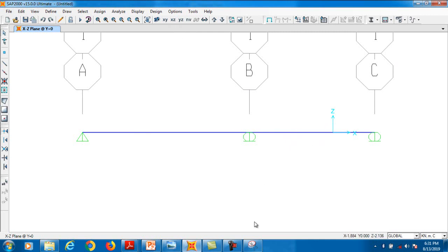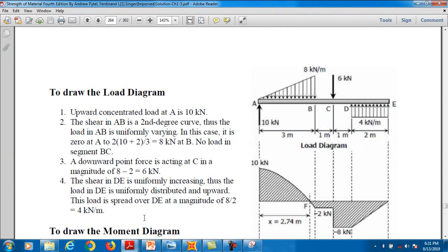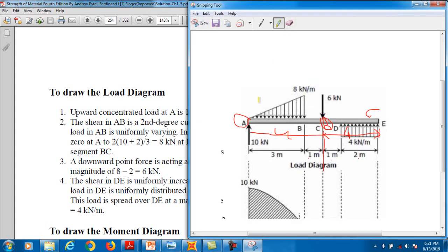So first of all, the second step is that we have to select the proper joints. Now if we come to the example, we see that there is a support and there is a support. One thing must be kept in mind: basically there is no support here. The arrow shape is the sign of a simple support. So you can place here a hinge and here a roller, or you can place here a hinge and there a roller support. It doesn't matter, you can replace these supports in case of a simple support.